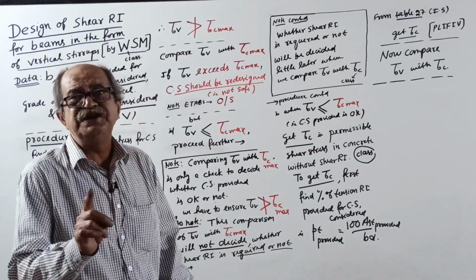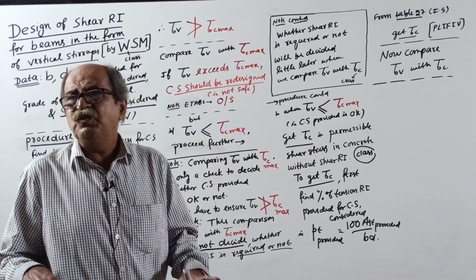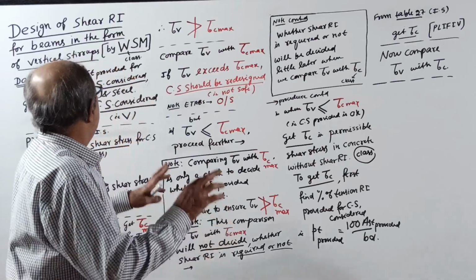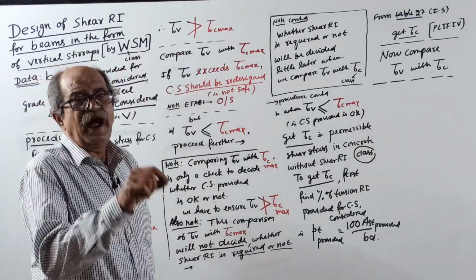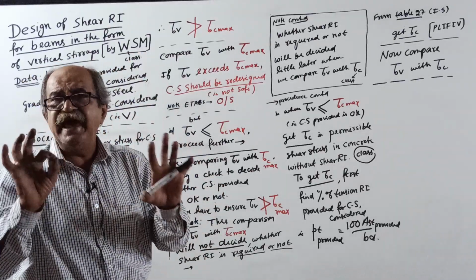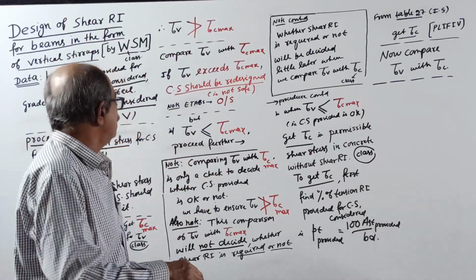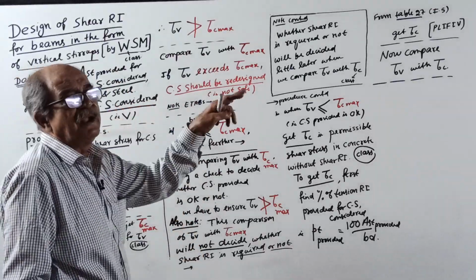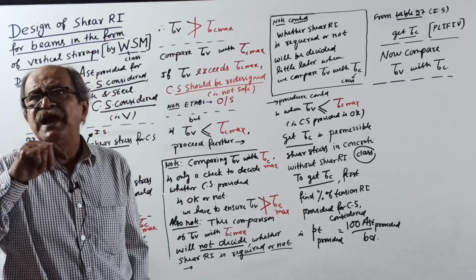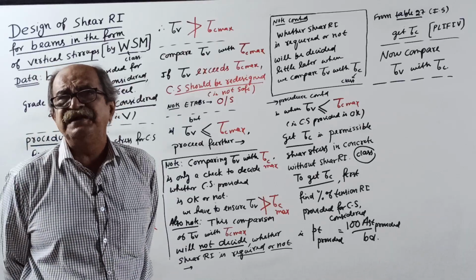But not for shear reinforcement. The way we proceed by the working stress method is 100% the same for the limit state method. Only some table numbers change and one extra term is added, called factored or ultimate.